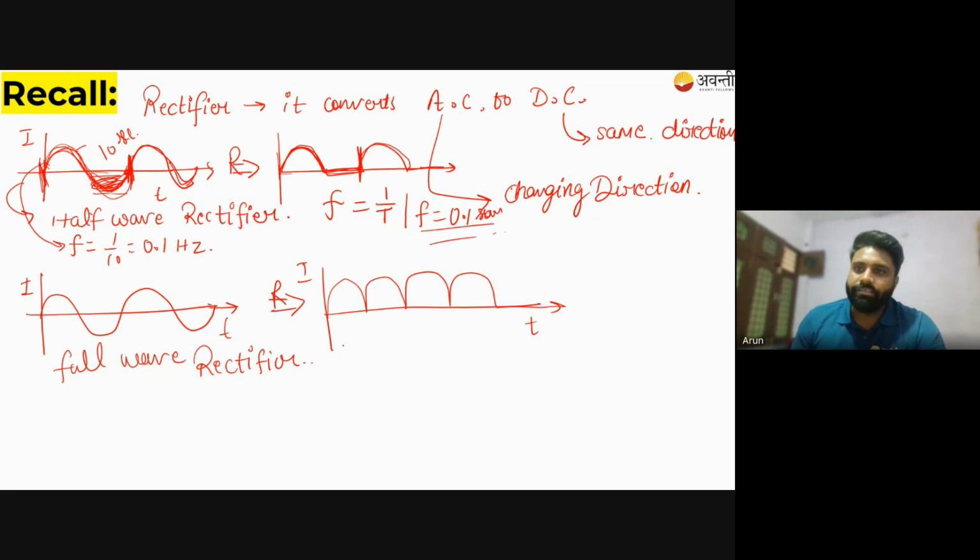The only difference is that you will have only the positive values of current, which means the current that flows after you implement a half wave rectifier. So the current that you will have is a DC current. You can treat that current as a DC source because it is not changing direction.